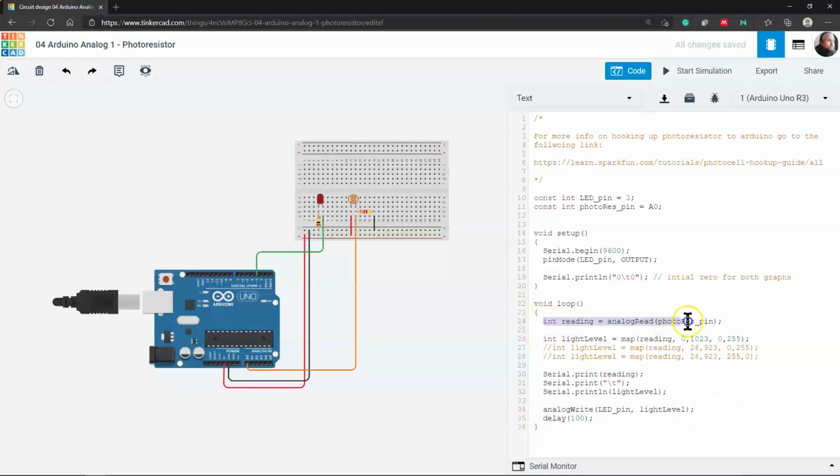So sense: read in and take a sample from the analog stream at this point in time. More signals could be coming in while we're doing work, but we're saying analogRead, give us a value to come in. Next, using the map function, remember, that takes your value that should be between this range, and maps it to an equivalent value between this range, from min to max.